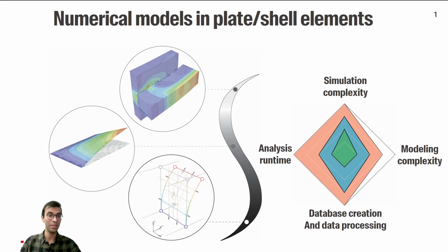The numerical simulation of structural components with plate or shell action typically lies along a spectrum of complexity. Specifically, the use of 3D brick elements with contact zones can be considered one of the extremes of this spectrum, while using 2D continuum shell-based elements, or only spring and beam elements as macro models, can be considered the other end of this spectrum.